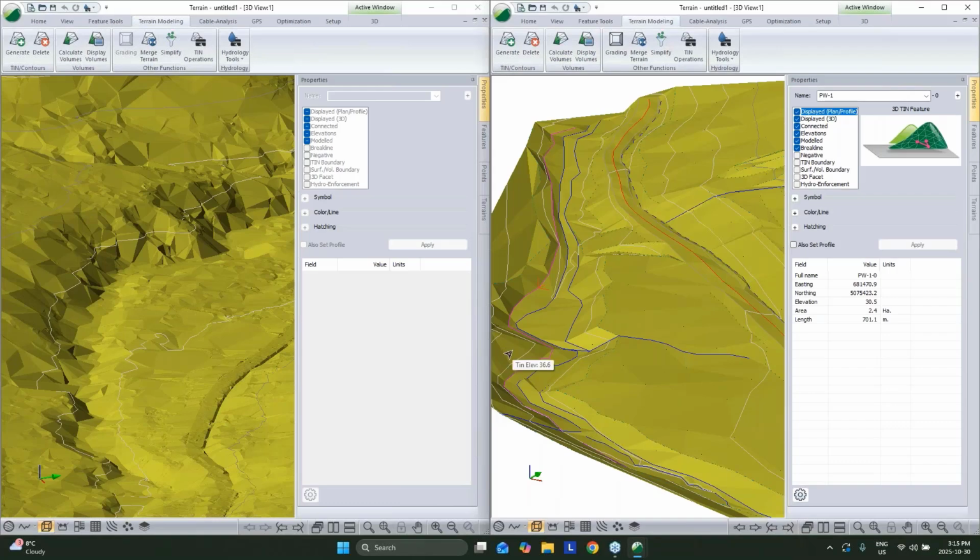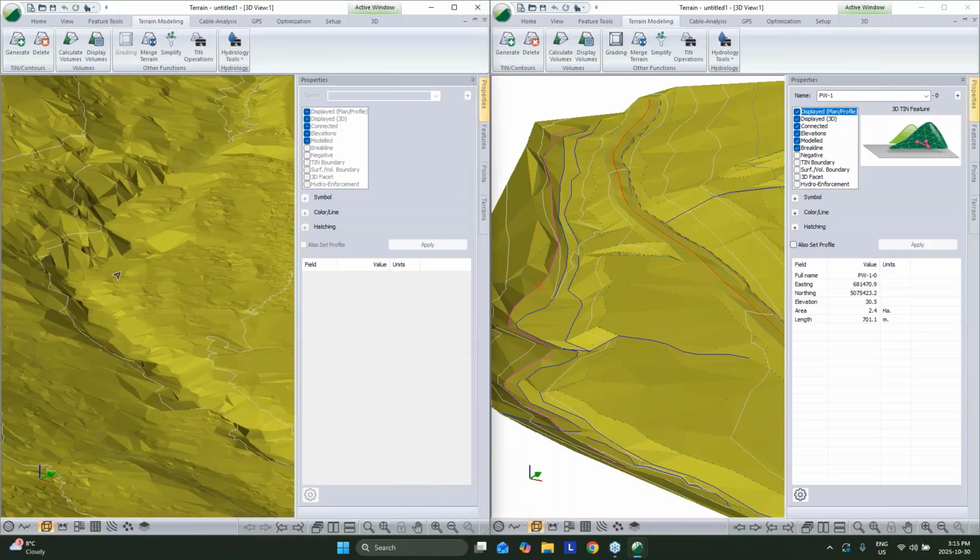So both of these are high quality surfaces, and they both have some pluses and minuses. Here there's vegetation over top of this creek, and when the LiDAR data is processed, we don't necessarily get ground points where we might have liked to. So both of these are pretty good surfaces.